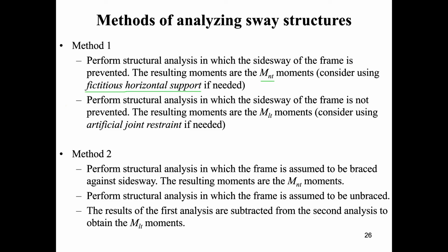Perform structural analysis in which the side sway of the frame is not prevented. The resulting moments are the lateral translation moments, M_lt. Consider using artificial joint restraint if needed.